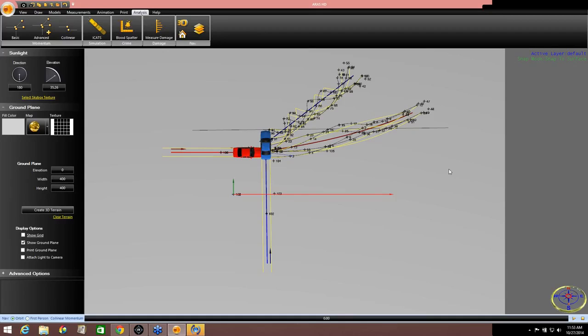If you see black marks, a gap, black marks, a gap, black marks, a gap, you're going to have something less than 100%. If you see striations the whole time, then you probably don't have any braking. It's just scuffing. It's just looking at your evidence in the road and determining what you have.